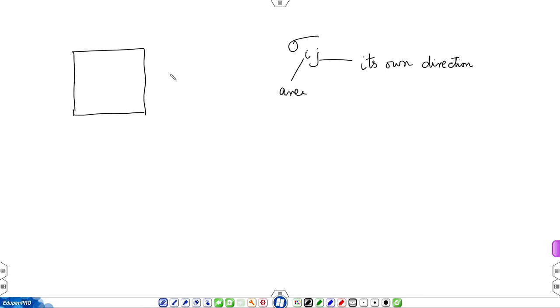So, I am showing a rectangular element. So, naturally we have Cartesian coordinates in the back of our mind. So, you can show the x and y coordinates. So, this vertical face, the one on the right, is an x face because the normal is in the x direction, and if I show sigma in the x direction, this becomes sigma xx.